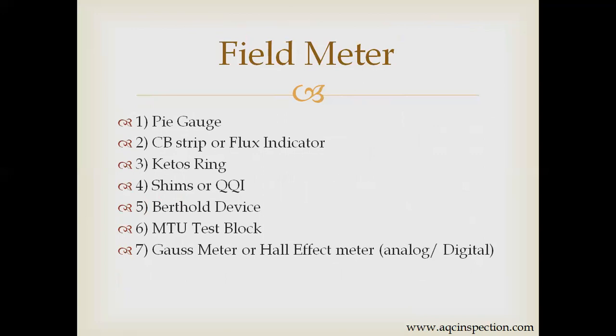Field indicators. Field indicators are used before commencement of inspection to prove that the system for MPI inspection which we use induces the proper magnetic field in the material.